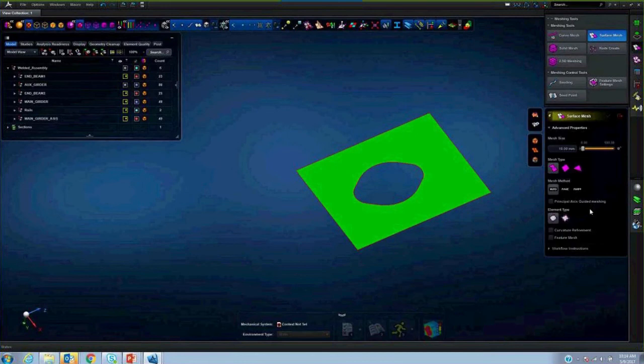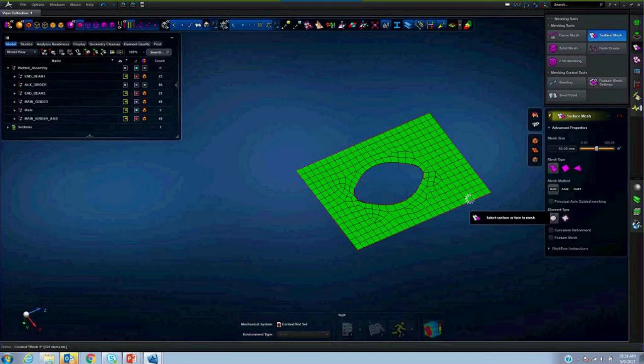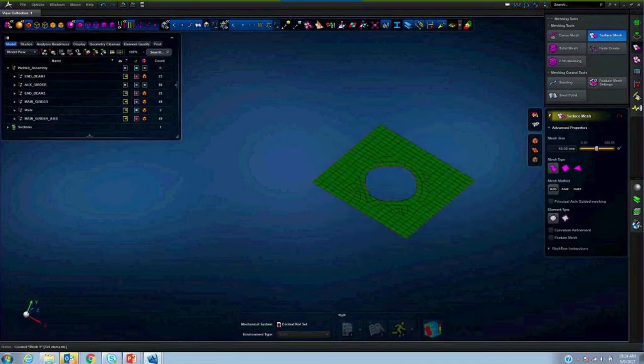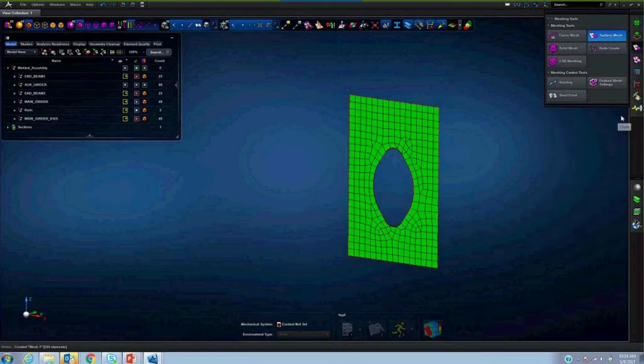And let's create a mesh for this part with, for example, 50 millimeter element size. Note that these structures are so huge, and this particular model is about 20 meters long. The normal element size that I might use is about 100 millimeters. And as you see here, even the inside bracket, I made it 50 millimeter.